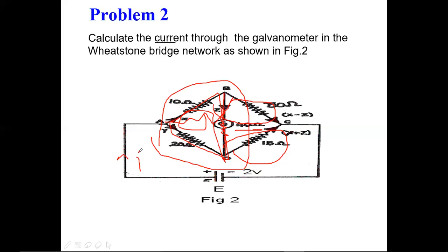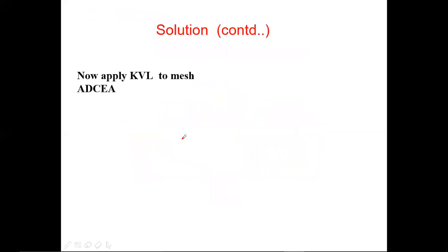If I know the current, based on the current division rule or some other division rules, you can find the branch currents. So there is a lengthy process if you apply the star delta also. Then is there any other technique? I can go for the loop equation, it is a little better for me, right? Other techniques will be very lengthy. If I go for the loop equation, I can easily get the common branch currents, right?